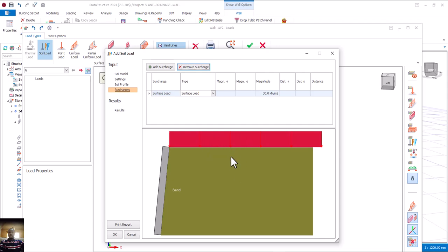The load that will be acting on this particular soil is vehicular load, isn't it? Let's forget about human beings. The major load is vehicular load. I'll now come to magnitude. If you don't know the value to use, the software has given us the maximum, 30 kilonewton per meter square. But if you know the load, good and fine, you input your load. When it comes to small vehicles, be it saloon, Honda, and all of those things, they are under HA load.